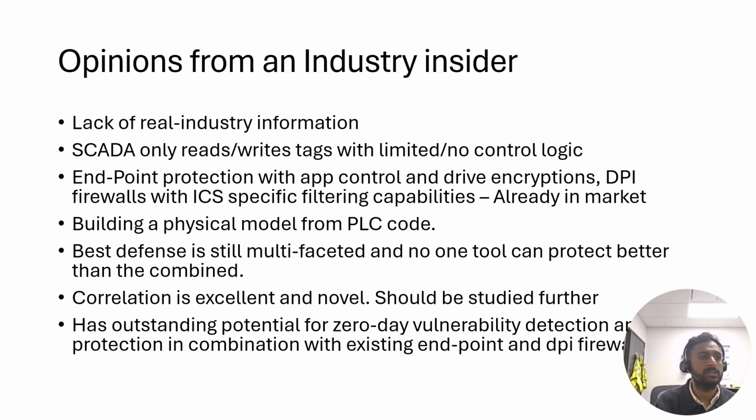Rarely is there any control logic or process logic at the SCADA layer. Almost always the process logic is at the PLC, your RTU, and DCS. So SCADA in pretty much every industrial case is merely a read/write to the tags within the PLC, but it's not actually doing any process control. Like there's no PID logic at the SCADA layer, unlike what the paper suggests.